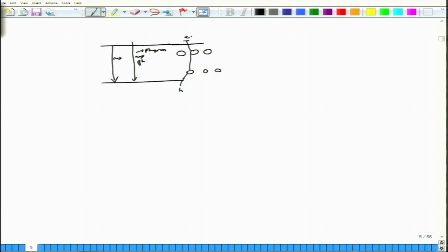So, this is one additional type of transition that may happen, okay, but you see that there are 3 processes involved, and therefore, the probability of this one will be quite small. Nevertheless, when it happens, it will lead to degradation of the laser performance, and therefore, this should be avoided. So, these are the donor states, or these are the acceptor states which are deep lying, okay, and these are the impurity traps that contribute to unwanted emissions.